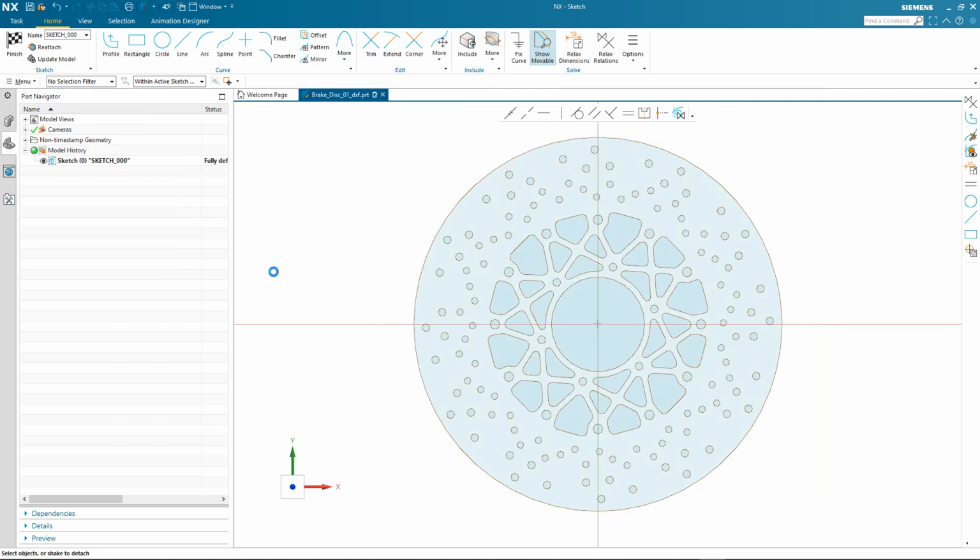Simply done. One important point to remember, that during the import, the brand new solver was recognizing geometric relationships. You'll notice some of these geometric relations appear when I select geometry on my 2D profile. Here I'm going to make a modification to the size of the outer diameter of the disc brake. As I select the outer curve, you'll notice I have equal radius arc and offset relationships appear within the graphics window. You can see how easy it is to make a change to this outer diameter.